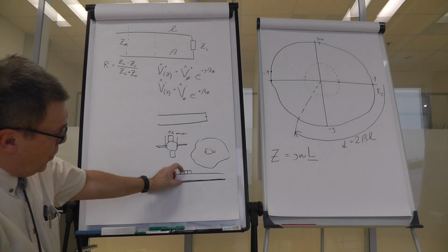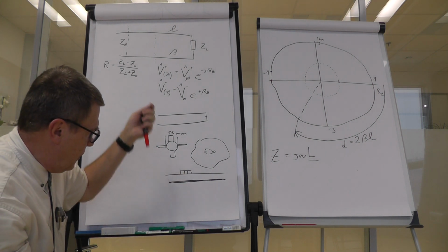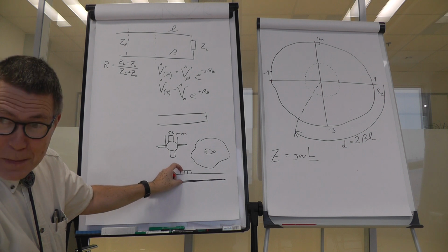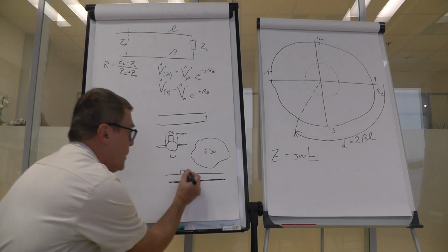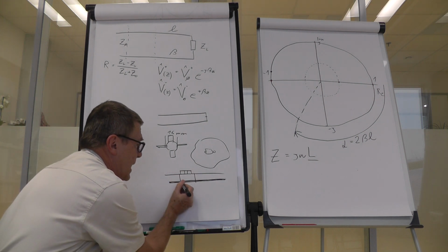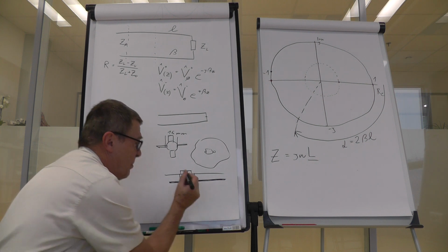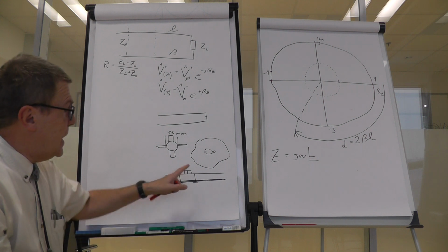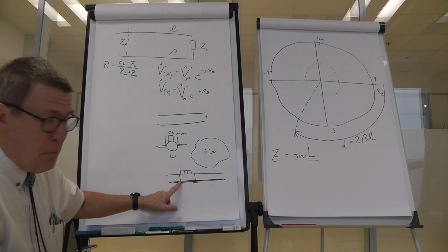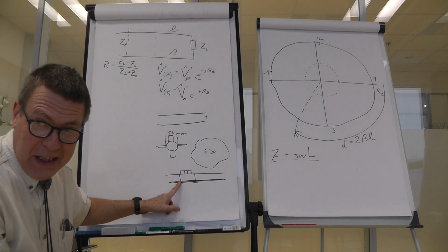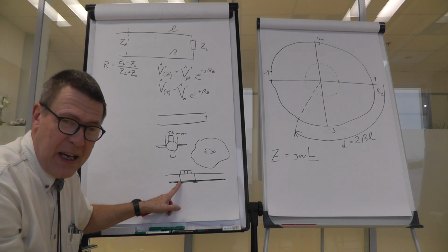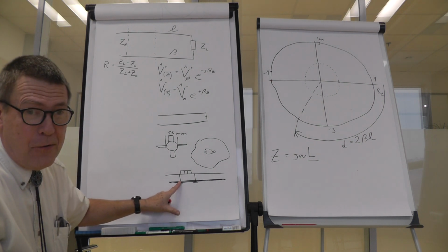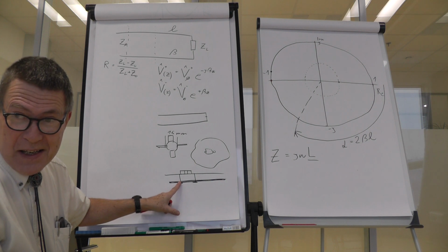The printed board is, let's say, 1 millimeter in thickness, so you have those 2 pads going downstairs, and you solder that well downstairs. But unfortunately, just this bent metal sheet has, say, 0.25 nanohenry of inductance.